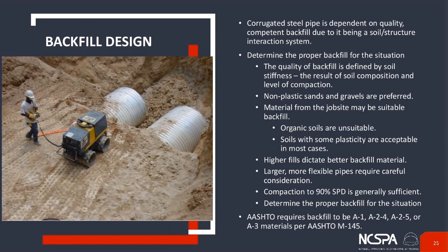We want to talk about backfill design. We talked about this some 2 weeks ago when we looked at structural design, but like Mike mentioned, it's also very important for the actual installation of the pipe. Corrugated steel pipe is completely dependent on the backfill due to the soil structure interaction.